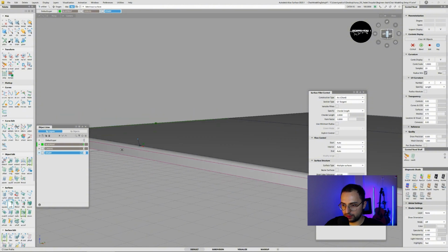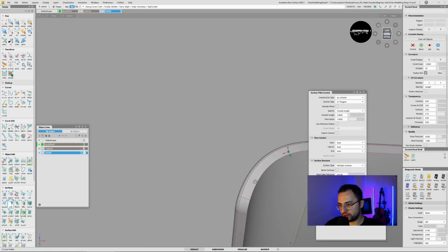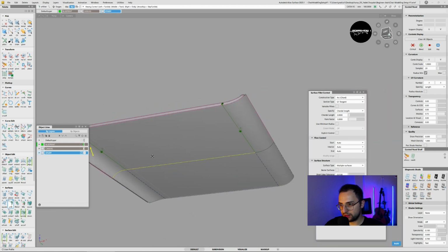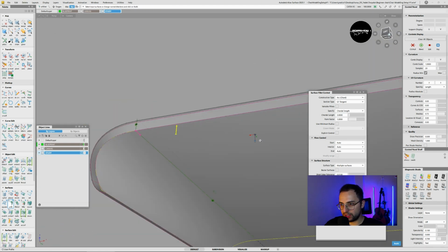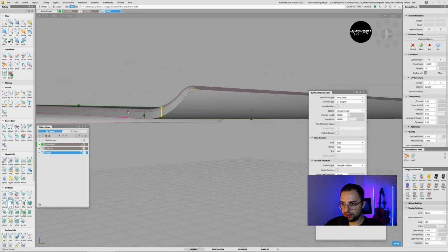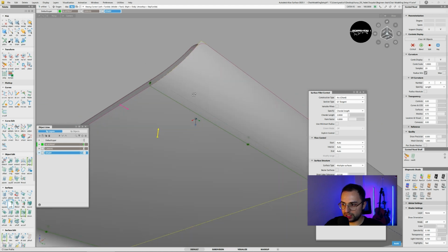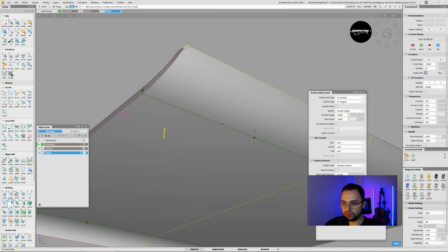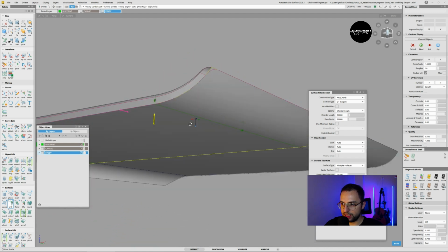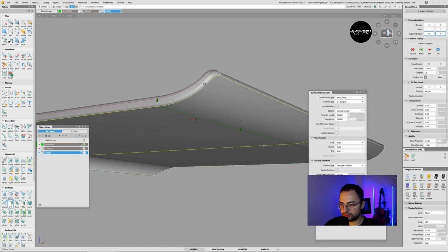For here as well, I'm going to pick all of the side surfaces and then the main surfaces. If you are not selecting these surfaces with yellow and purple covering indicators, there might be a tangency issue between the surfaces that you want to do the fillet operation on. If so, control the alignment first and then filleting second. Yeah, perfect.